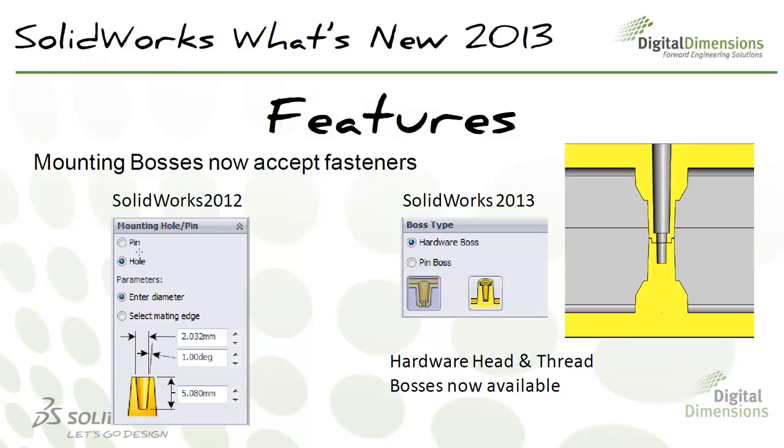Now you still have the pin and hole, but you also now have this hardware boss where you can have a through hole down to where the threads go in. So this is where you can see the screenshot I have here. You can actually have a through hole and a fastener to go through here. So you can see the fastener type of boss is now available to you. And they also made it a little bit easier to understand all the different dimensions, and there's more dimensions available.